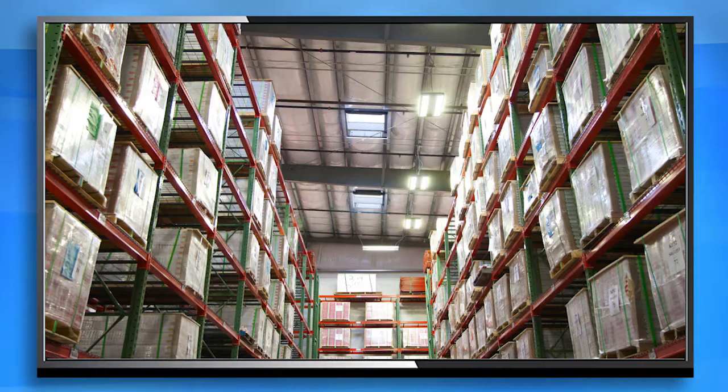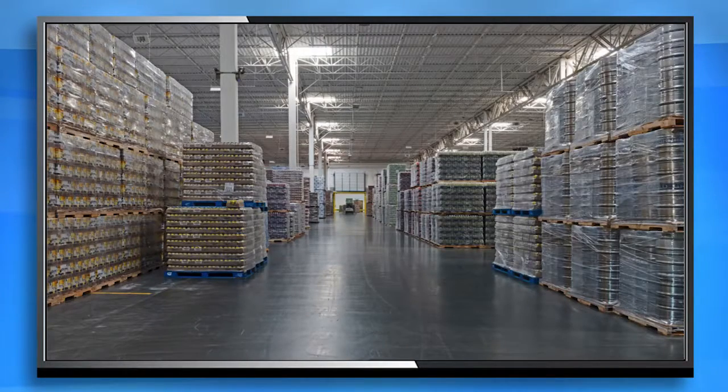Great, thank you. So what are some applications that are best suited for daylighting? Great. Well, what I want to do is show you some pictures so you can see how daylighting impacts spaces. So the first one is warehouses. Warehouse is a great application for using daylight. You have high ceiling mounting heights, and we can use larger skylights to bring light into the space. You're going to save 40 to 70% of your energy through the skylights, and you get the benefit of occupant well-being, improved productivity, and reduced safety issues related to lighting quality.